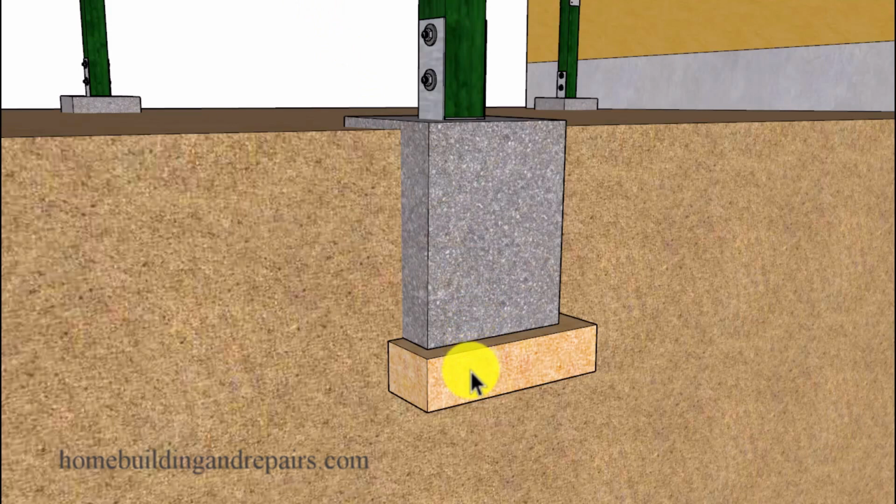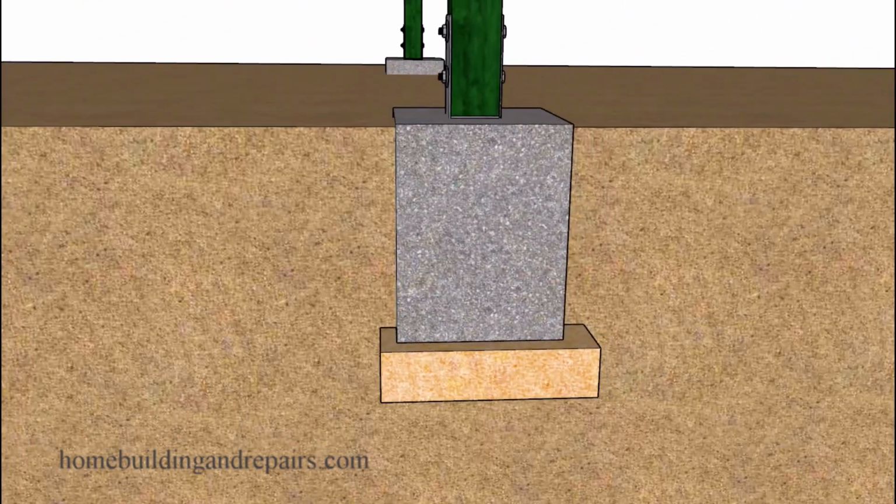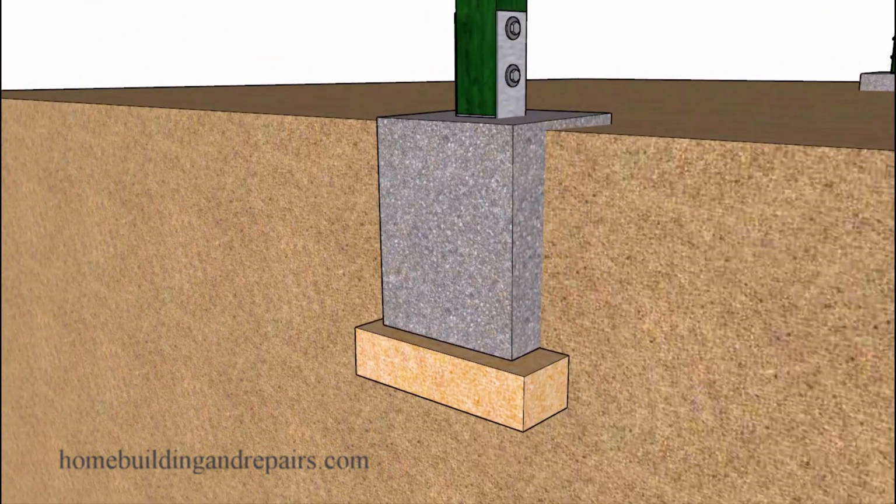or soil surrounding the footing, specifically underneath the footing, that was not properly compacted. And this can happen when you over dig the footing. Let's say you needed a footing that was going to be 12 inches deep and you dug your hole 14 inches and instead of leaving it, decided to fill it back up with soil that wasn't compacted.